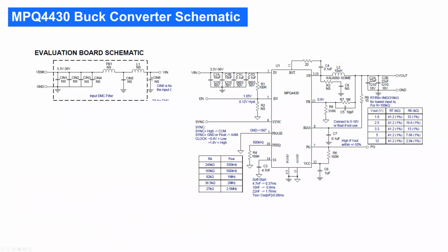The schematic we have already shown, as there are input decoupling caps. Now we removed, I think, C1A. Now we have C1B and these smaller capacitors. And we have on the back side an EMI filter. Typically, we use a fourth order EMI filter with 2 inductors.